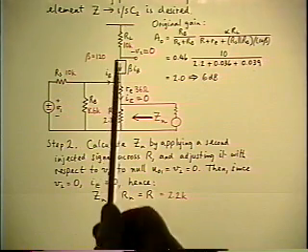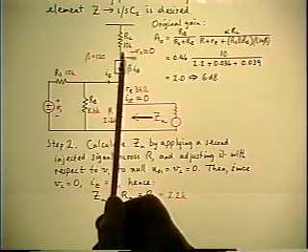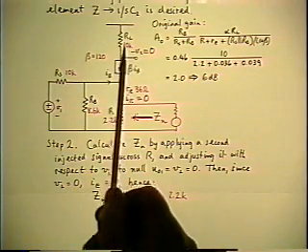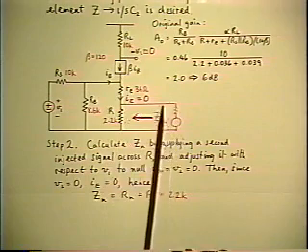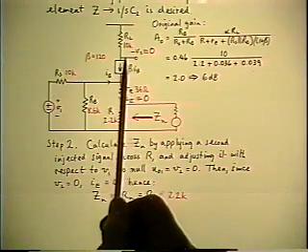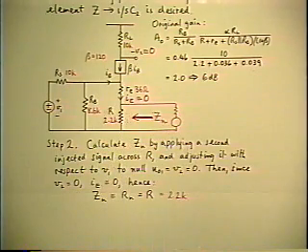It's a logical sequence of argument to say what is the consequence of having adjusted the null. And the consequence is all of the current from the second source must go down the R because the null propagates. This is why setting something to 0 is so useful. Because if one thing is 0, a lot of other things are 0 too.